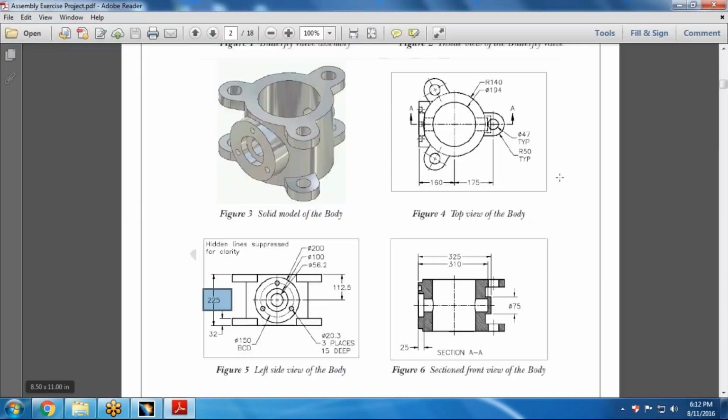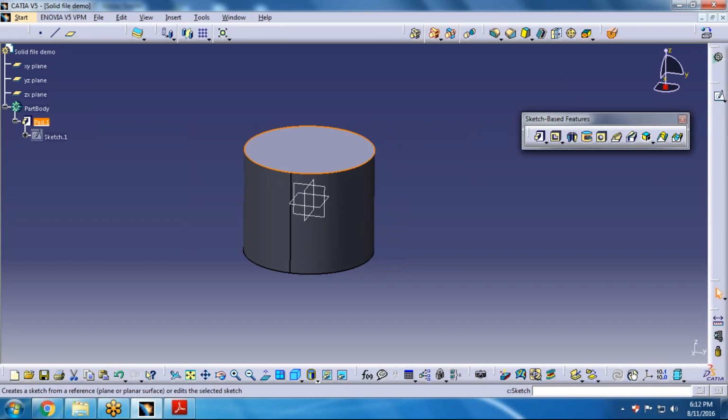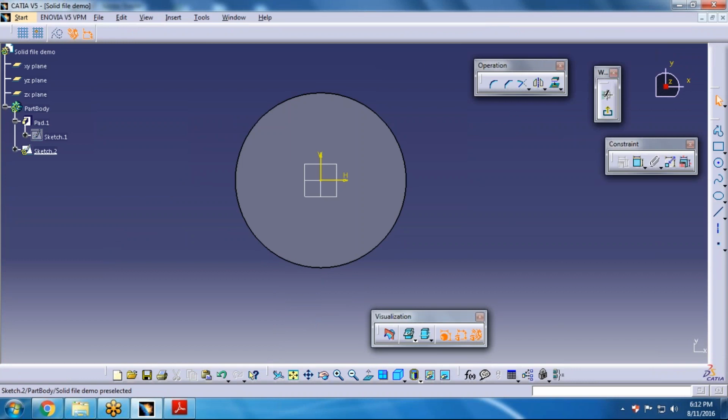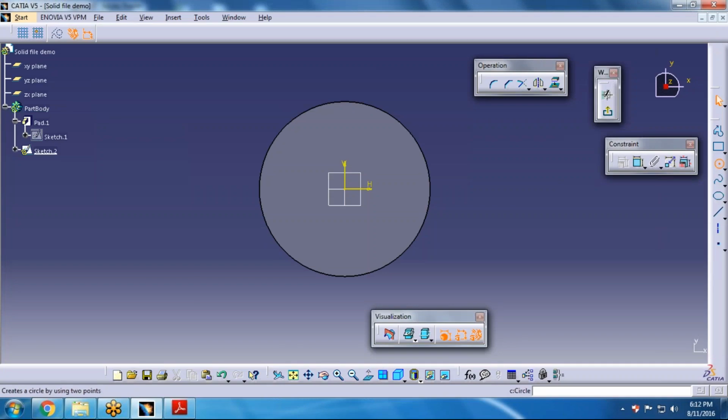Now after that we can do one thing. We can see there are flanges there. I want to create these flanges, like one flange I need to define. So I just need to go on this face basically and switch the sketches. So now you are in sketch number 2. You can see there is a distance they have shown us, that there is 175 till the center of this circle. So I'm just giving one circle like here, and I'm just giving the radius of this.